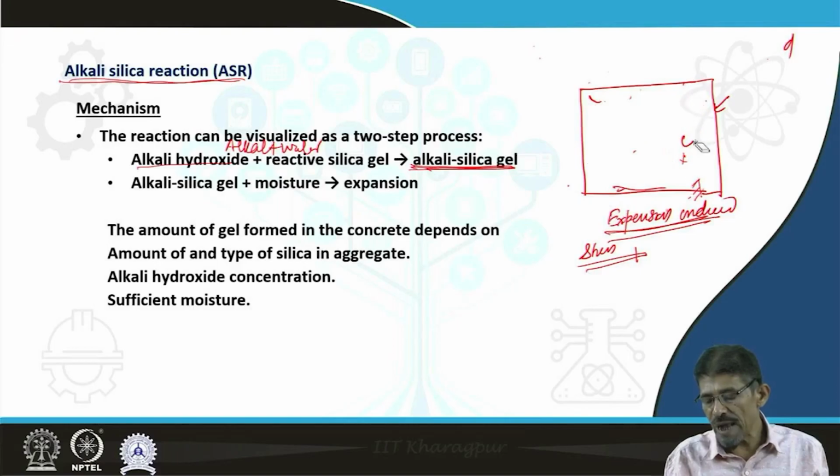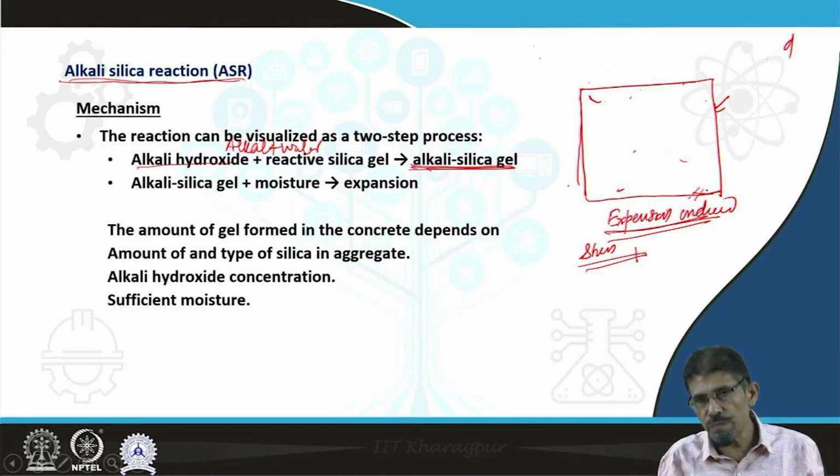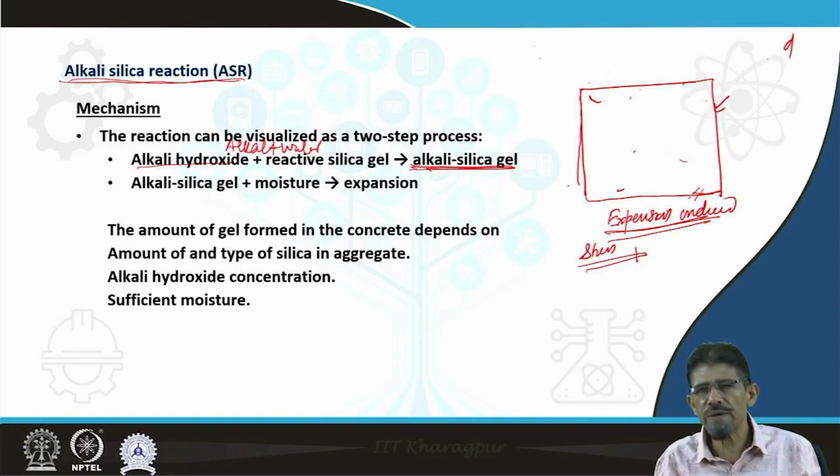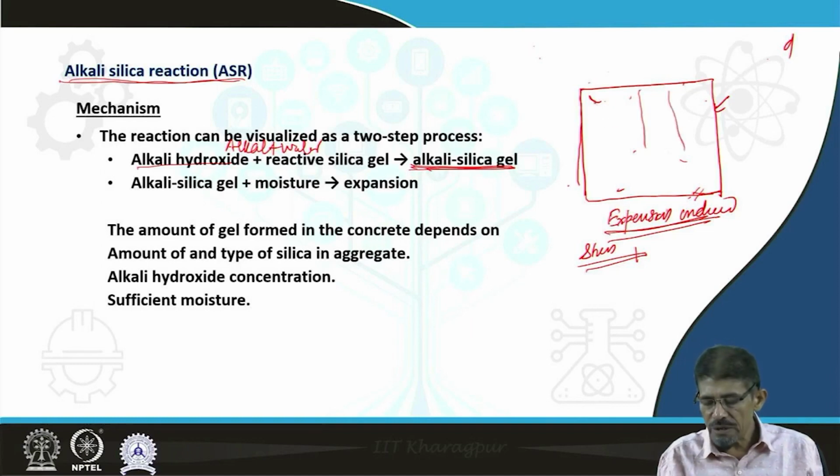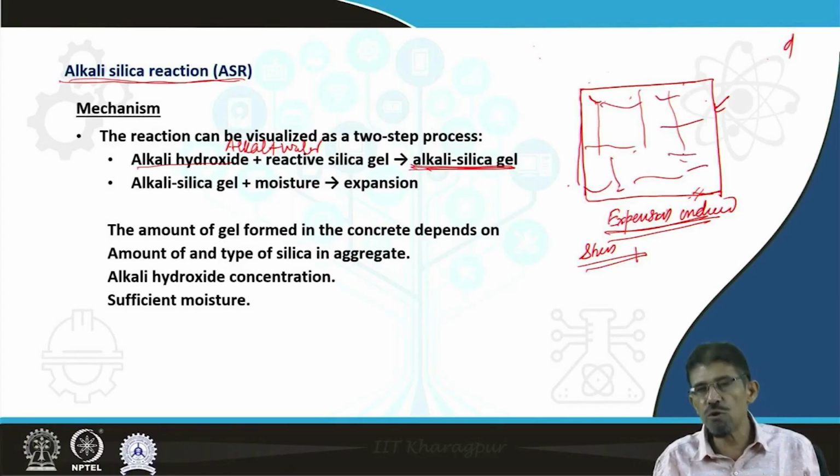These cracks are alkali aggregate induced expansion in volume, resulting stress, and adjustment of the concrete is going to provide some fractures, cracks and others. It means such cracks and fractures develop to adjust with the stress developed due to the alkali silica reaction.